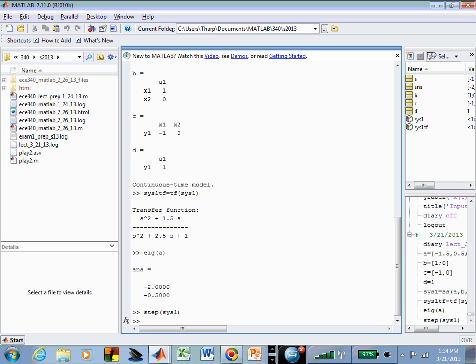What's going to happen to your current? It'll stop flowing, won't it? Once those capacitors charge up, and they're going to charge up with this e to the minus 1/2 t and e to the minus 2t structure. That's based on our eigenvalues. The eigenvalues are directly related to the time constants. Now we have to look at their reciprocals to see the time constants. Since these are real, that's pretty easy to do.